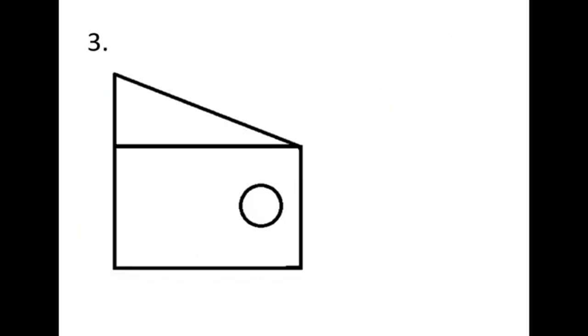See, I have a rectangle, a triangle and a hole inside the machinery part. Now, as I told you, I need to take the bottommost line as the x-axis and the leftmost line as the y-axis. If I take the x-axis and y-axis, next we need to divide the compound plane figure into a number of plane figures for which we have the centroidal formula.